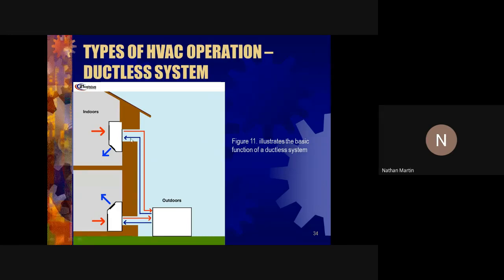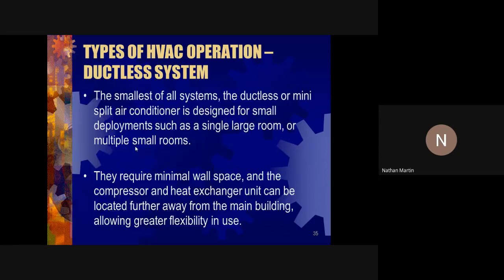So they take into consideration that you might mount it directly behind the wall that the evaporator is mounted on, or to the left or to the right. There are knockouts provided in the unit for that, so you don't have to cut out the side of the unit. It's already there. All you need to do is knock it out and then install the unit.